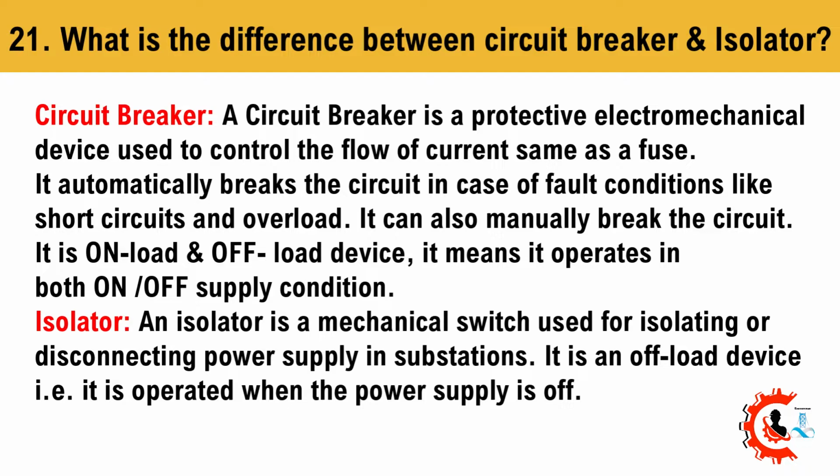Isolator. An isolator is a mechanical switch used for isolating or disconnecting power supply in substations. It is an off-load device. It is operated when the power supply is off.